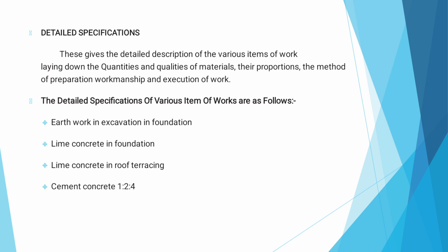The bottom of foundation trenches shall be perfectly leveled both longitudinally and transversely, and the sides of the trench shall be dressed perfectly vertical front and bottom up to the least thickness of loose concrete, so that concrete may be laid to the exact width as per design. Okay. Then fines and water in foundation trench, filling, and then finally measurement.